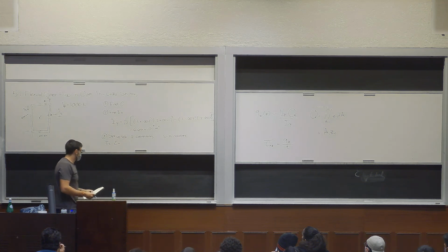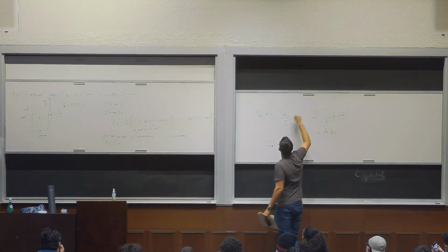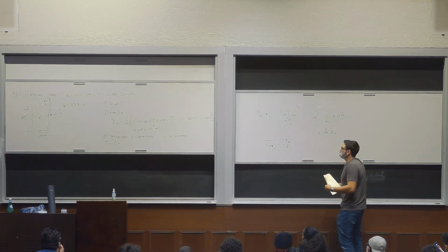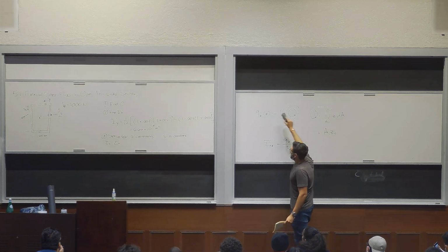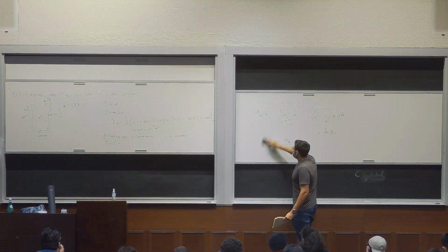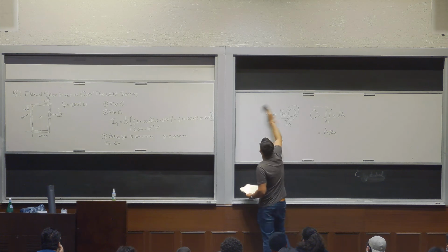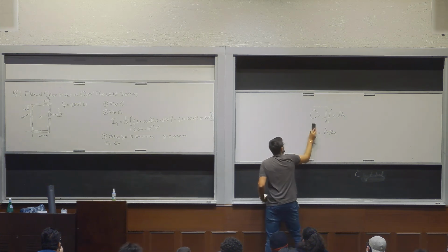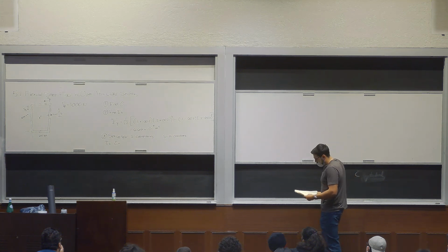Then the next step is solving for these big Q's. That's still the variable of interest here, because from these big Q's, these first moments of area, we can figure out these shear flows, and from the shear flows, shear stress. From the shear stress, we know if the structure is failing or not. So that's what we got to do. Find Q, big Q.